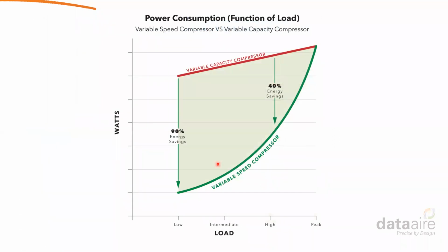So this slide shows a curve for the compressor. We've talked a lot about an economizer, but we can't forget about the compressor. The compressor needs to be as efficient as possible because it may operate thousands of hours a year depending on the weather at the site. And this slide compares energy consumption of a digital scroll compressor and a variable speed compressor operated by a VFD.